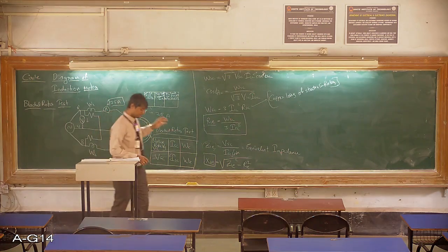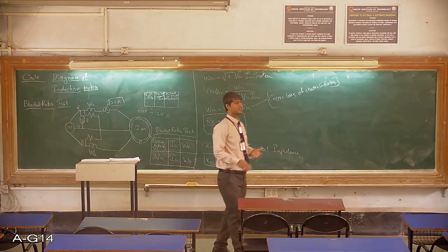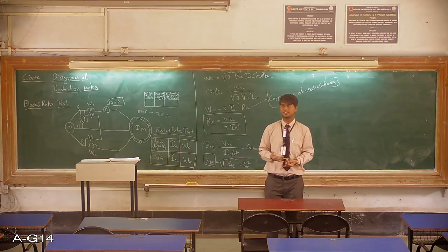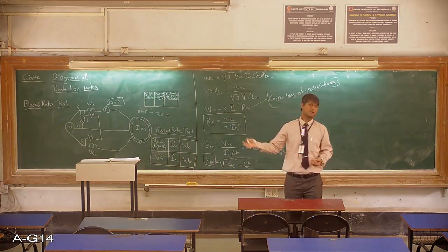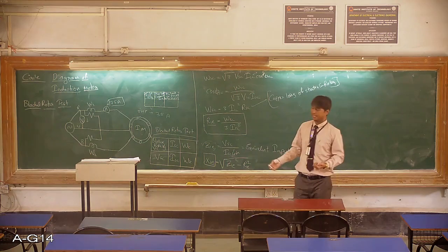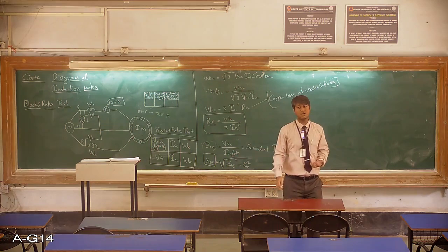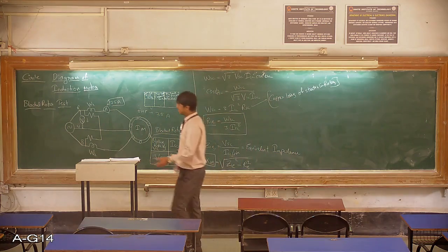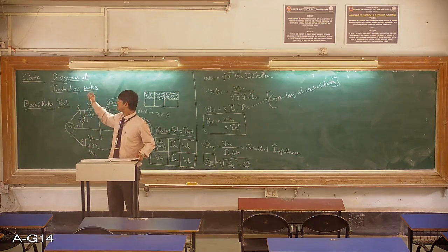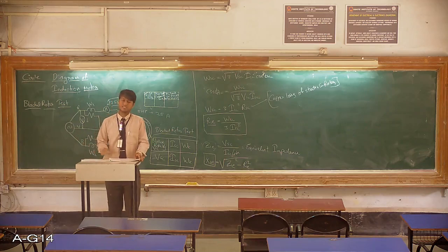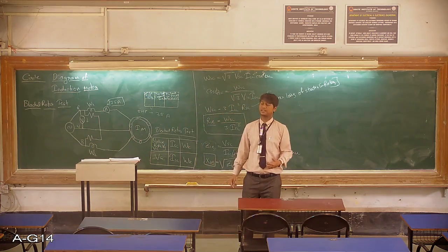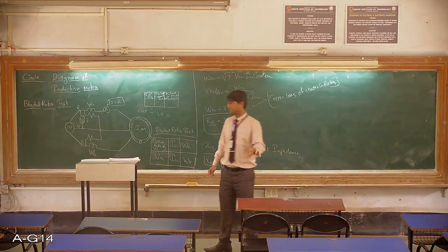By conducting the no load test and blocked rotor test, we are going to calculate all the parameters like R1E, X1E, R0, X0, IC, IM, and from the no load test iron loss, and also friction and windage loss, and these variable losses like copper loss of stator and rotor. All these parameters can be calculated for the induction motor by conducting no load test and blocked rotor test, and also by plotting the actual circle diagram. By actually plotting the circle diagram, we are going to find many more things like the parameter like torque, and even in torque so many different parameters are there.